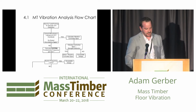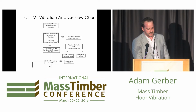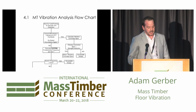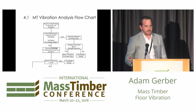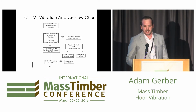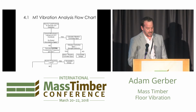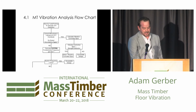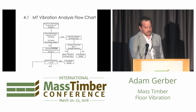Basically, doing your sizing for strength and deflection like you always do. Consult your manufacturer's literature and verify that the stated assumptions apply. If they do, you can use those resources directly to choose a vibration-controlled span or if you were already okay, you can keep the span that you had in the first place. However, in cases where those assumptions do not apply, we have to go through a Design Guide 11 approach as a reasonable next step.